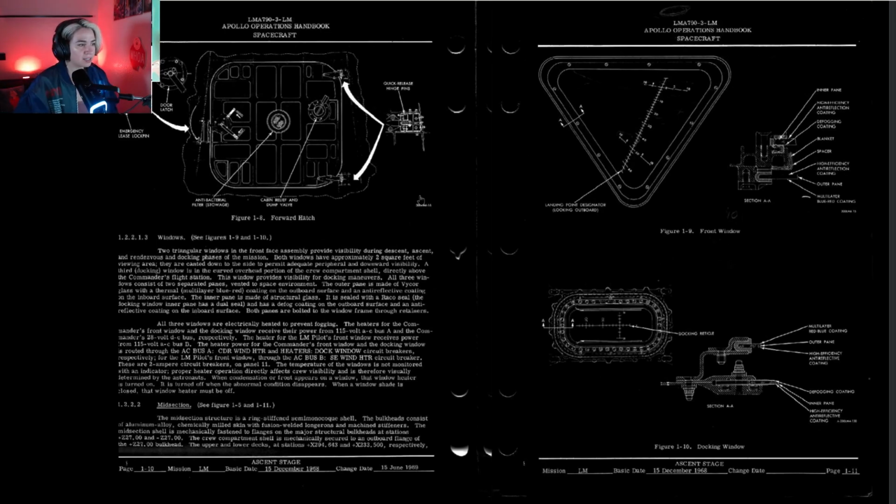The bulkheads consist of aluminum alloy, chemically milled skin with fusion welded longerons and machined stiffeners. The midsection shell is mechanically fastened to the flanges of the major...